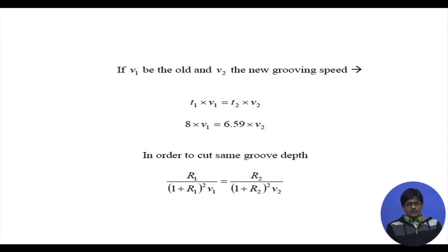Now, in order to cut the same groove depth, the job is remaining same, the groove depth has to be the same, and once again we remember that in the expression for groove depth there were so many other terms, but none of them are changing. Just to remind you, cross section of the water jet is not changing, pressure is not changing, density of water is not changing. So, we absolutely do not have to bother about the other terms, but these terms are changing. Loading factor is changing, velocity is changing, therefore, groove depth has to be now kept the same.